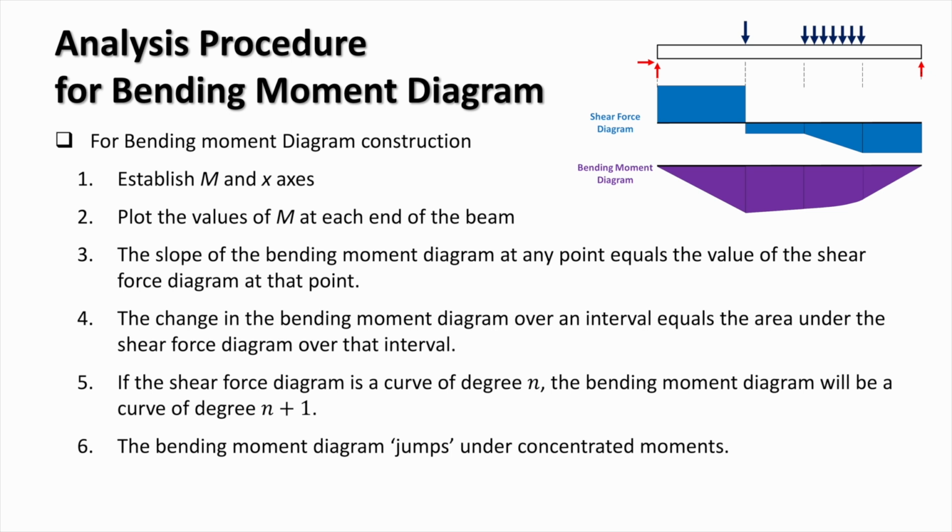As a result, the shape of the bending moment diagram can be predicted directly from the behavior of the shear force diagram. Concentrated moments produce sudden jumps in the bending moment diagram, while distributed loading causes the bending moment to vary continuously along the beam.